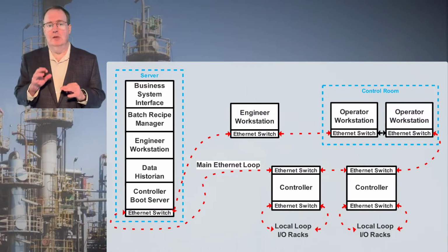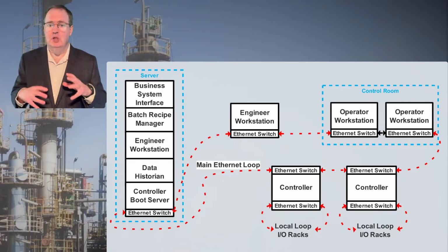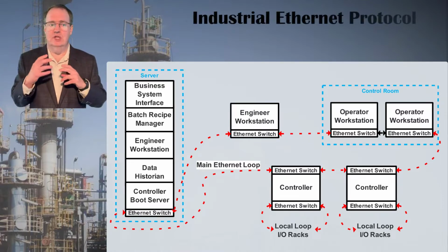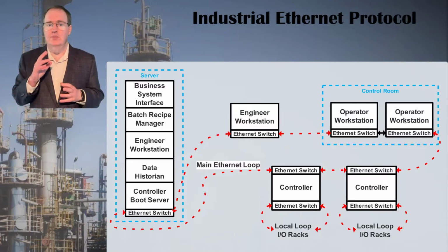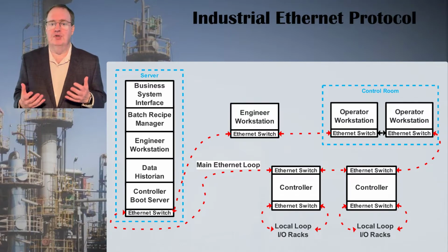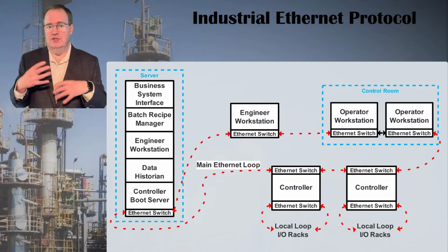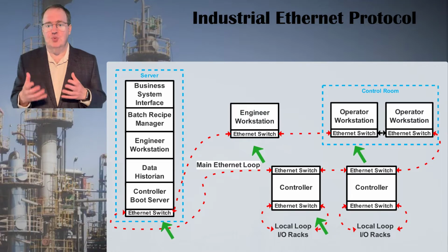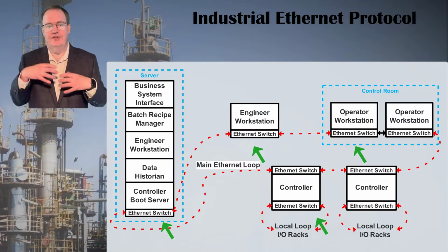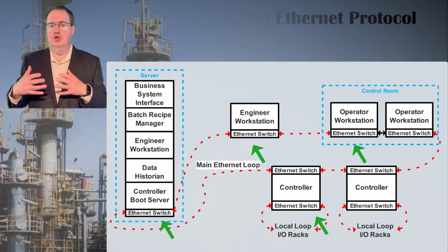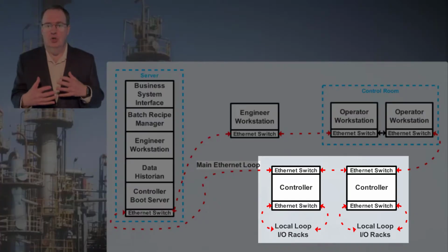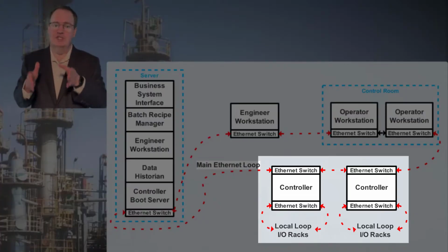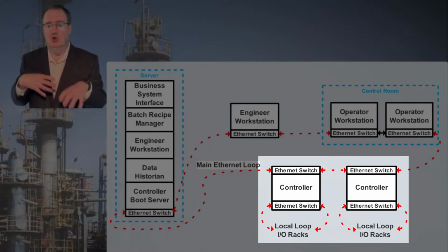The computers that make up a control system are connected by cable and communicate using the industrial Ethernet protocol, which is a communication standard for network computers, very much like the various protocols that define how the internet works. Every device has an Ethernet switch, just like the internet, with an address that allows them all to talk to each other. There are controllers, which are the super fast workhorse engines that talk to the sensors, pumps, and valves, run feedback loops, digital logic, and sequences.